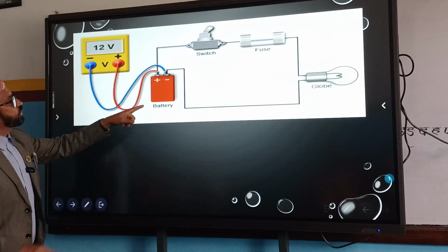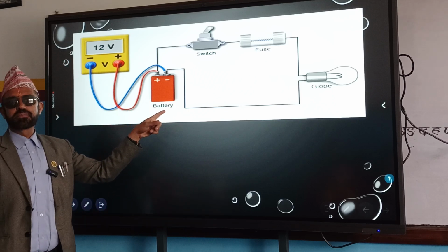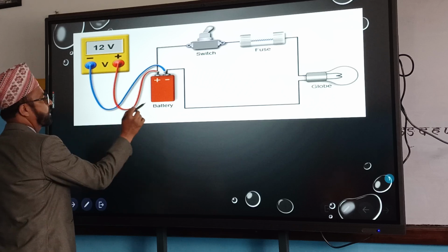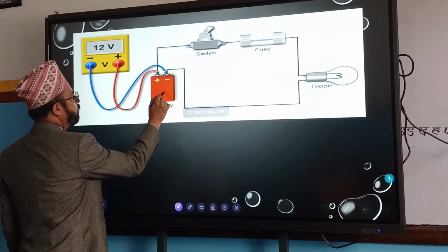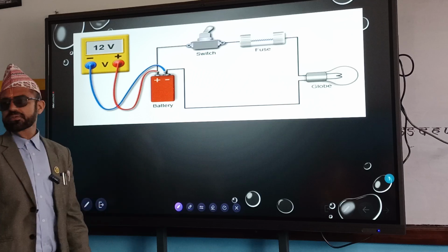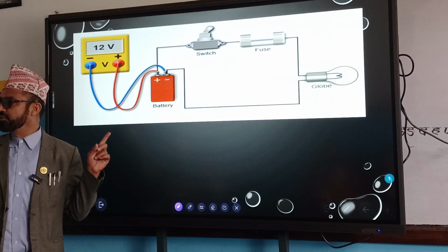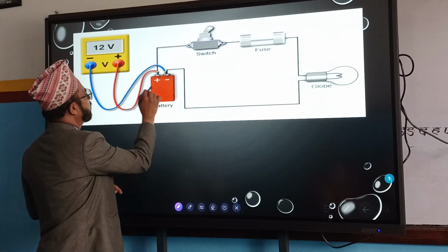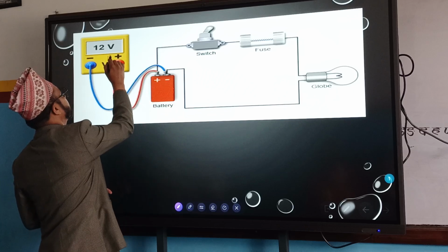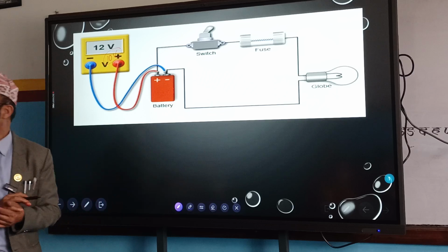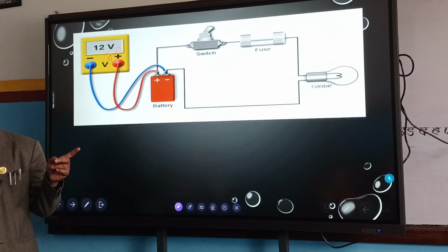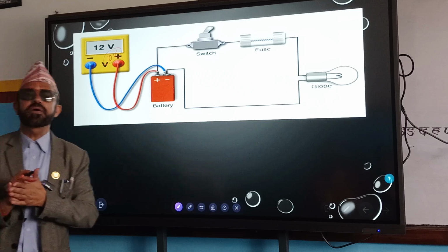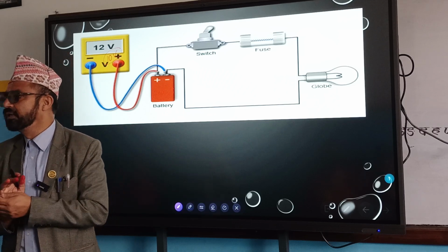Okay, here is the source of electricity. The battery is here, right? In the battery, suppose it is written 12 volt. So what is that 12 volt? EMF. That 12 volt, what is written? That is EMF. But when it is connected to the circuit, then it may show here how much? 10 volt. That 10 volt is PD. So here we can define EMF and PD in a different way also.